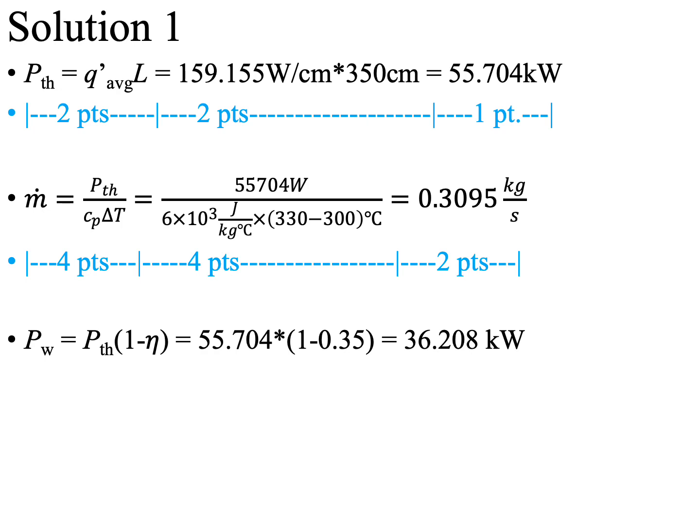Problem 1c: you know the reactor thermal efficiency, that is 35%, and you want to calculate the waste heat power. 35% means that 35% of the heat produced will be converted to mechanical or electrical power, and the remaining 65% is the waste heat, which has to be rejected to the environment.